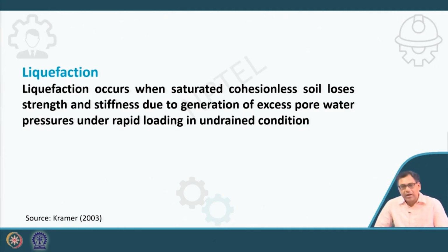So right now I am defining it, and I will follow this definition: liquefaction occurs when saturated cohesionless soil loses its strength and stiffness due to generation of excess water pressure under rapid loading in undrained condition. Here the rapid loading is treated as the cyclic loading, that is, seismic earthquake loading.